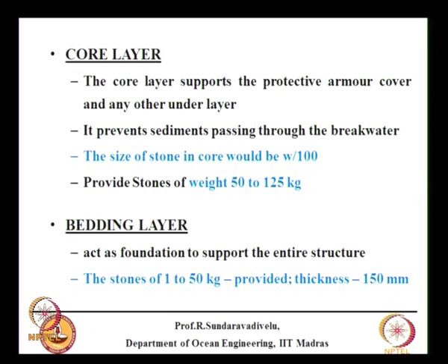You cannot put your core stone directly on top of the seabed, because the core stone size is bigger, 50 to 125 kg. So, when you put it, it will get into the seabed and it may get settlement also, and the proper distribution of pressure will not be there. For that reason we put this.